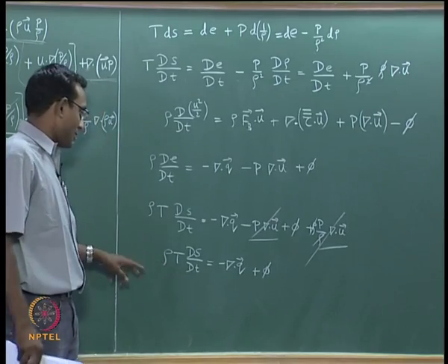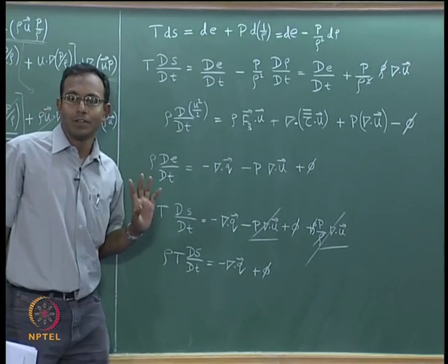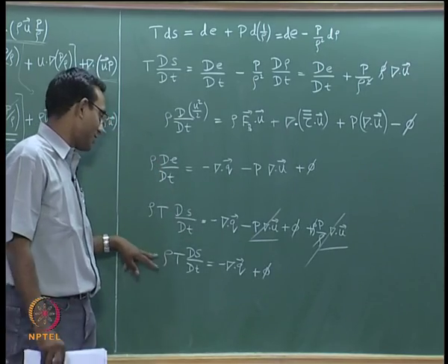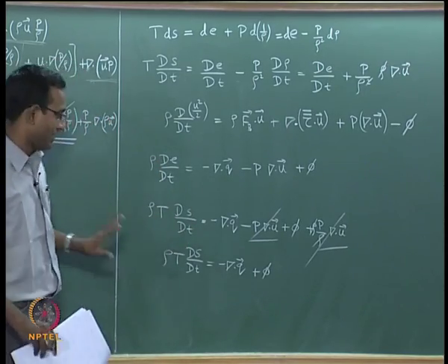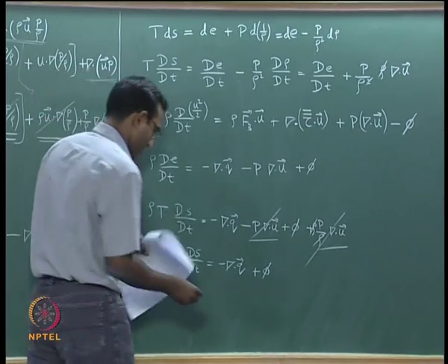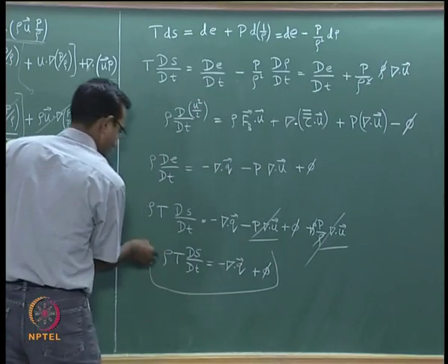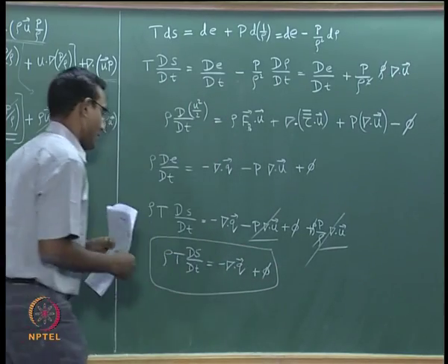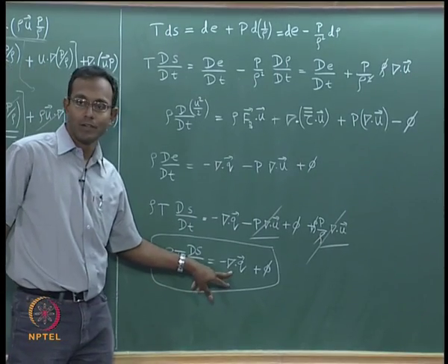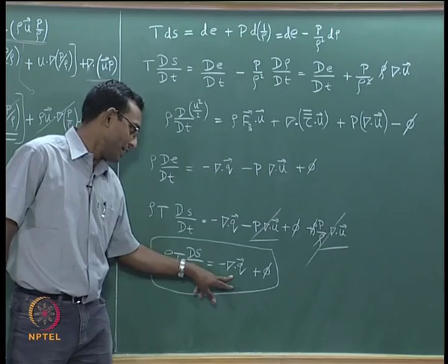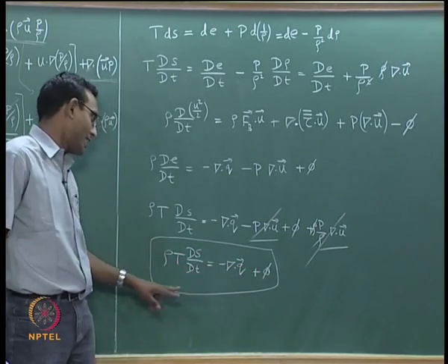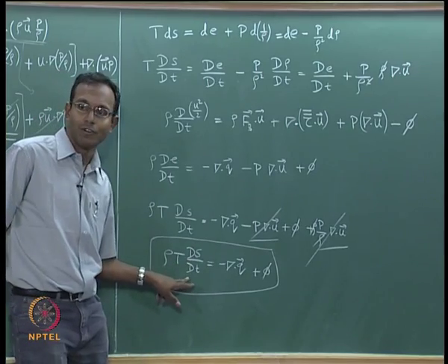Okay. All this while I have always used compressible flow, where density was changing. It so happens that I used my continuity equation, so that the density always comes out of my derivatives, but I know that it is compressible flow. Okay. So, the essential part of this particular statement is that if I do not have heating of my fluid, either by heat conduction or by viscous forces, I will not have any entropy change in my fluid flow.